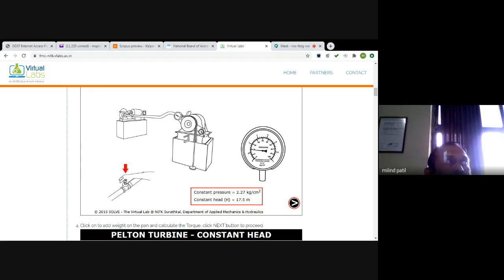This means bar. How? That's your fundamental knowledge. Pressure P is always equal to rho g h, where rho is density, g is 9.81, acceleration in meter per second square, and h is the head of the water column. You can calculate the water column pressure.